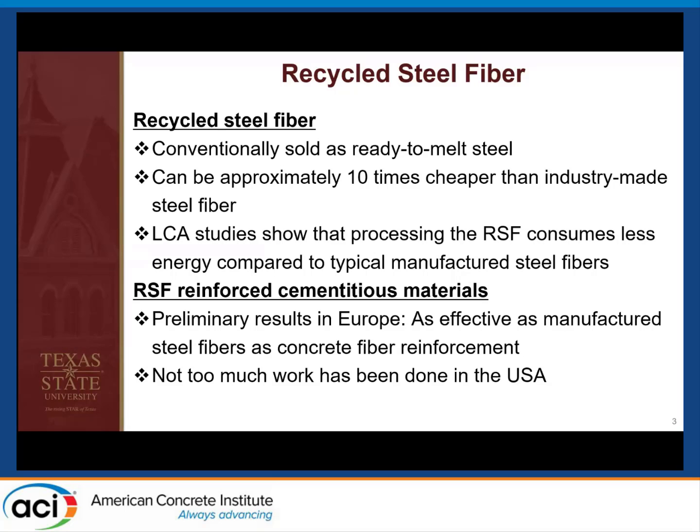Therefore, the question is, what does tire recycling do with recycled steel fiber? Unfortunately, the recycled steel fiber is conventionally sold as ready-to-melt steel. Because it is sold as recycled steel for making new steel products, the price of the recycled steel fiber can be 10 times cheaper than industry-made steel fiber. Also, life cycle assessment studies show that processing the recycled steel fiber consumes less energy compared to typical manufactured steel fibers. Therefore, we think recycled steel fiber can be a cheaper solution to fiber reinforcement for cementitious materials.